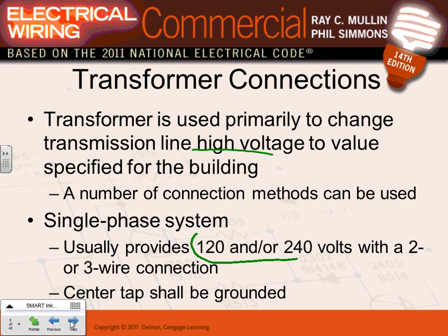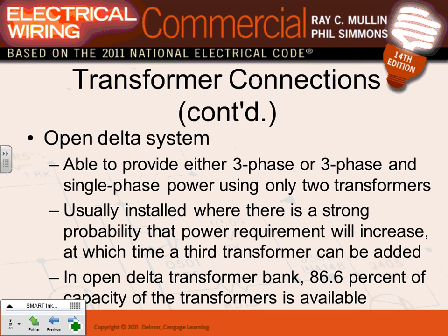Here's one transformer they can get. We did it in the residential. It's called the 240/120 three-wire, right? That's your residential used in the US a lot. It comes from a center tap, a grounded center tap transformer. I have a picture of this one. You're going to look at it in a second here. That's what we use in residential.